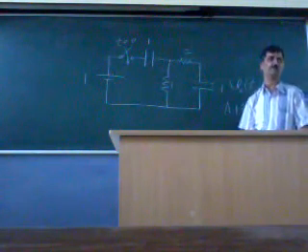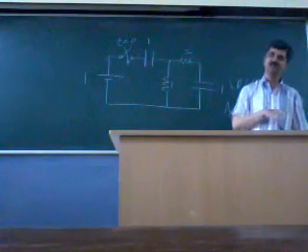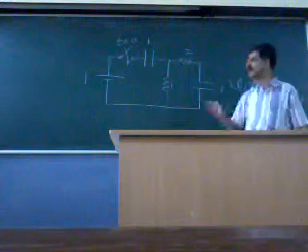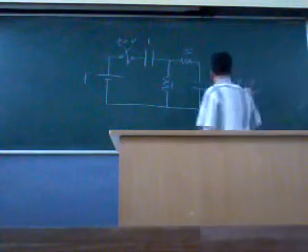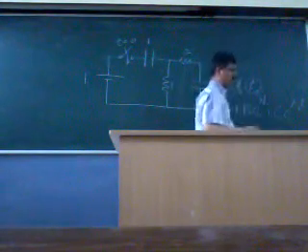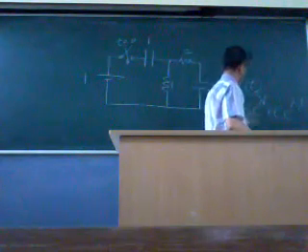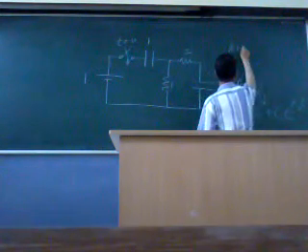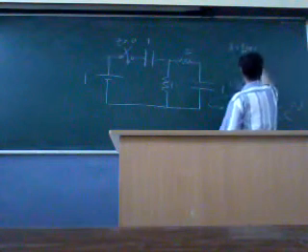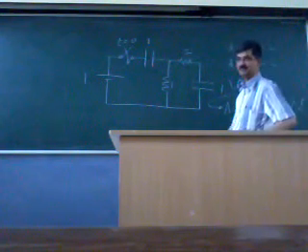We can also have a capacitor charged with some different voltage, and for that the initial conditions will change, and for that also we have solutions. Right now we presume a zero initial condition. So this is the assumption for V0(t). V0 equal to 0 makes each exponential 1. So A plus B plus C is the output voltage. This must be equal to 0. So A plus B plus C is equal to 0. So we say A is equal to minus B minus C.